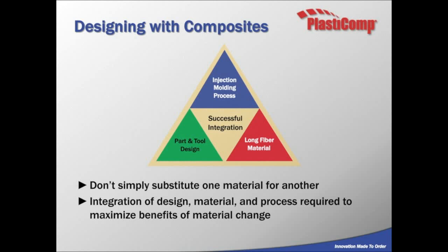And you want to think about how that flow is traveling through the cavity, how it's taking shape, what the fiber orientations are as they're flowing, but also the process itself. When you're dealing with injection molding, there are going to be process settings and injection speeds. All of these things need to be optimized.